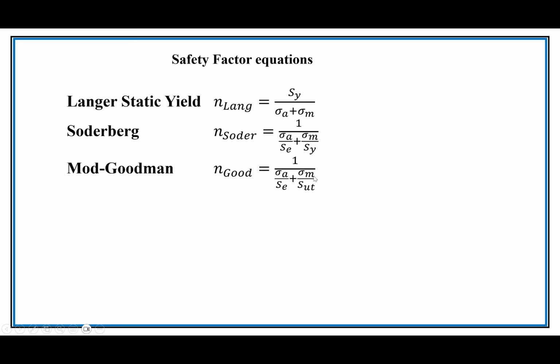The Goodman, I think, makes more sense than Soderberg, because failure as fatigue is the part breaking apart into things. So when it comes to the static element of it, the mid-range element, we could make that same comparison of the thing coming apart into pieces, as opposed to comparing whether it just bent and won't come back into its original position when it comes to yield. So that's why I would maintain the Goodman has a little bit more sensible comparison, apples to apples wise.